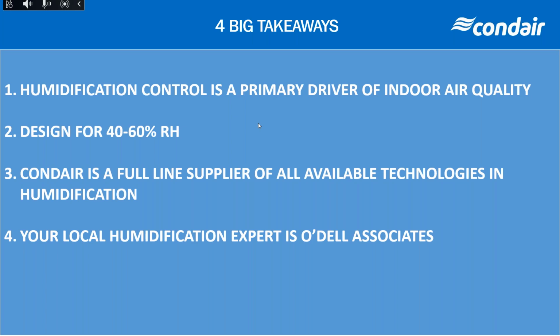So maintaining the RH is simply by putting humidifiers into the air handling system to put more moisture back into the air after the outside air is brought in the middle of winter. So that's on the humidification side. There are going to be areas where you might find dehumidification when you get above 60% in the middle of summer, but generally hospitals are cooled, so that kind of takes care of itself, just by virtue of the cooling side of things.